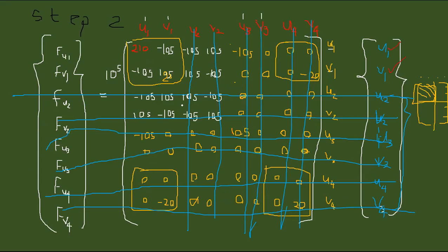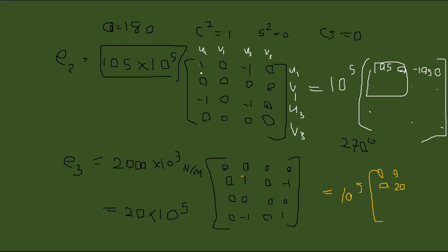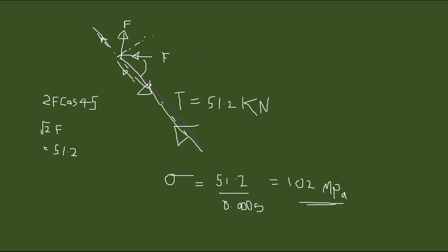Similarly, you can calculate the stresses in the second member as well, right? This is how you normally do a truss. So for this part, when you calculate the member forces, tension and compression, there's a method to transform it back and take it. But in this method, if you know the nodal forces, you can simply take the components at any node and find the compression or tension using the equilibrium at this joint, and using the knowledge that you gained from high school, right?